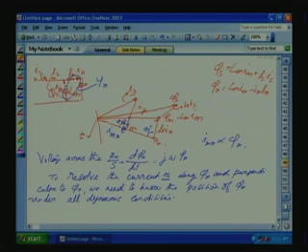So, we need an equivalent circuit which is valid under all dynamic conditions. That means, whenever the IS varies or the flux amplitude varies, psi m amplitude varies, psi s varies, how the relative positions of all these vectors change. From that, find out psi r and resolve IS along psi r and perpendicular to it, and keep the current component along psi r constant. So, psi r will be kept constant.